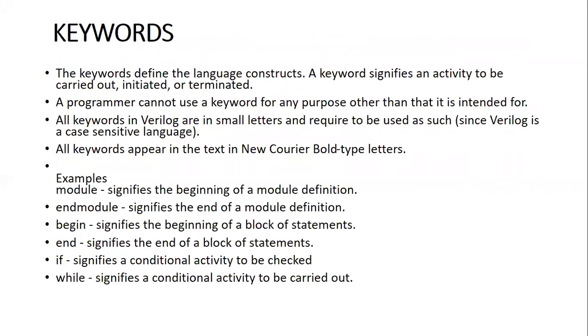Now what are keywords? We'll discuss the lexical tokens. Keywords are something which define the language construct, which is used by the language, which we cannot use as an identifier. A keyword signifies an activity to be carried out, initiated or terminated. So a program can use a keyword only for the purpose it is designed and not for any other purpose. Verilog is case sensitive. All keywords in Verilog are to be in small letters.